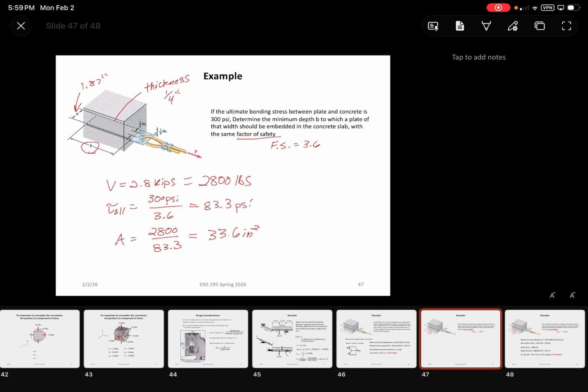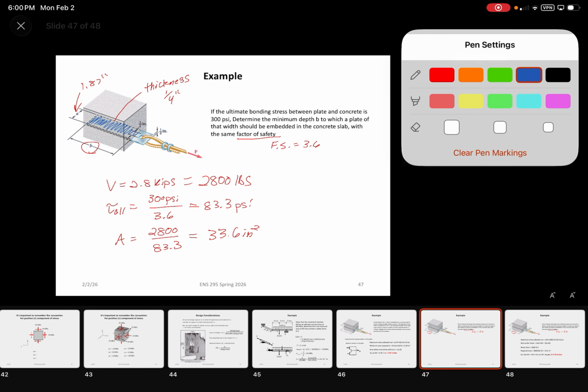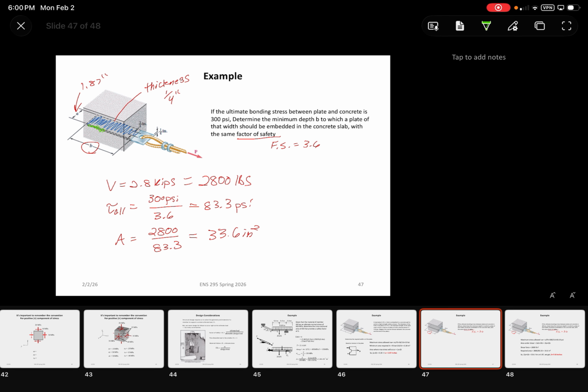Who here has a guess? Yeah. Split between two surfaces. So there's like two, top and bottom, right? Yes and no. There's side surfaces too. Yep. So, what he was saying is you have a top surface here that's subjected to shear. It's reflected on the bottom as well. But what you also should note is that you've got a side surface just like that, and that's reflected on both sides of the plate as well.